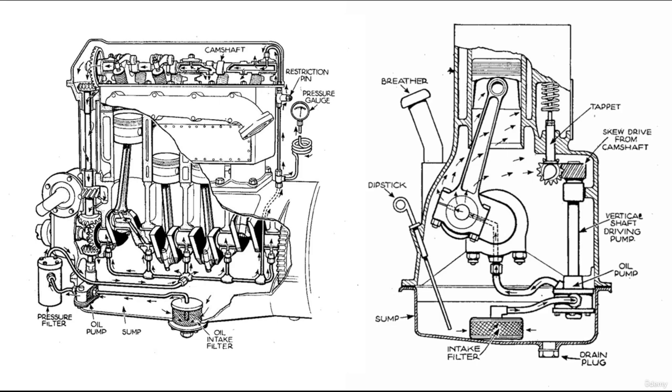As oil leaves the pump, it passes through many passages. These passages restrict oil flow, and these restrictions are what cause oil pressure. So small passages cause the pressure to increase, larger ones decrease the pressure. This is why excessive bearing clearances will decrease oil pressure.